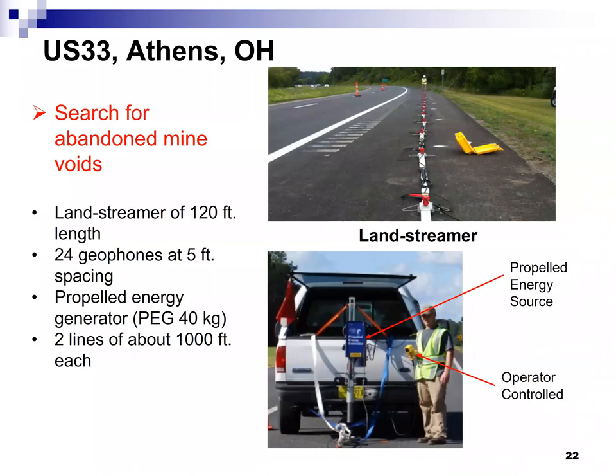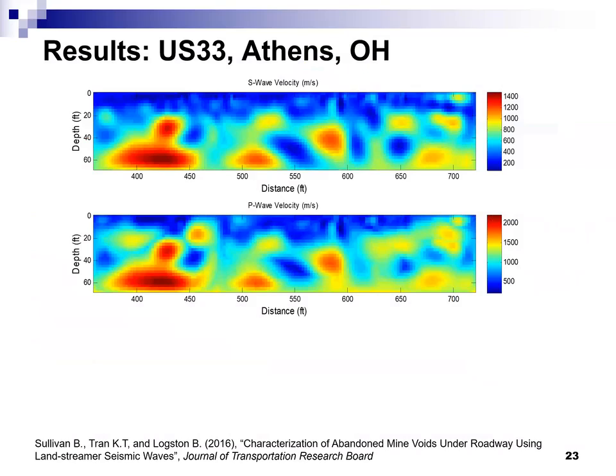Using a motor here, press the button, this one goes up and down. So we can select different heights of the rope, so we can apply different energy if we want. And we can also change the impact plate a little bit to play with the frequency content. So what is the predominant frequency range? We only use from 5 to 50 hertz.